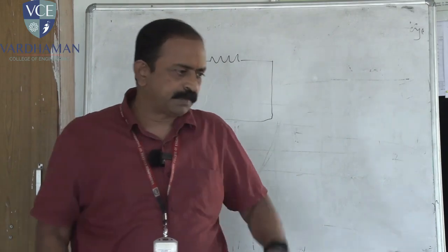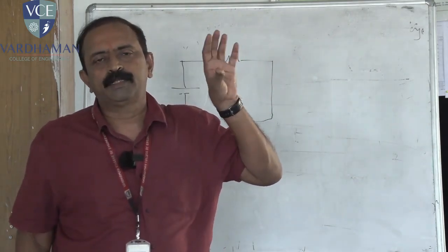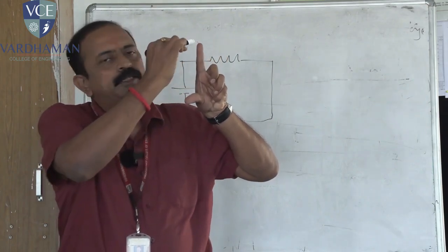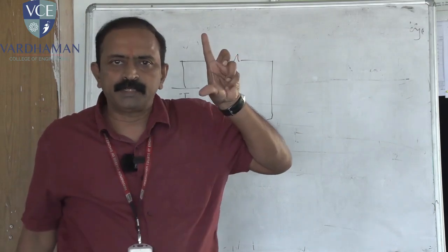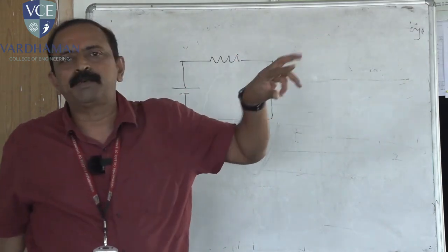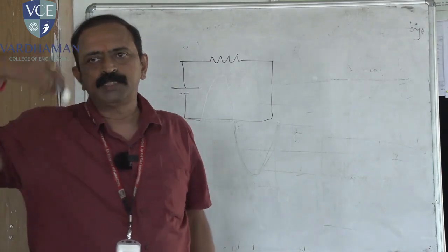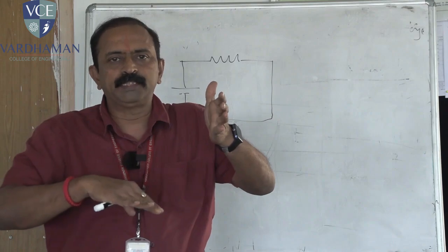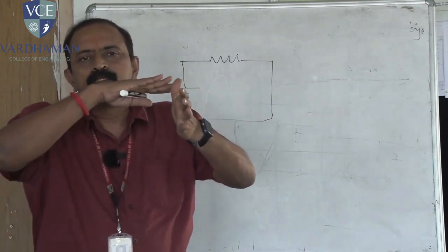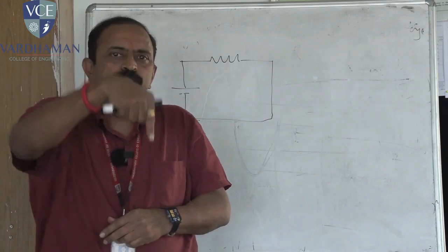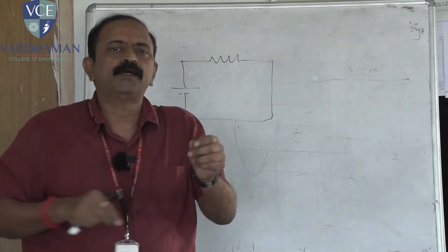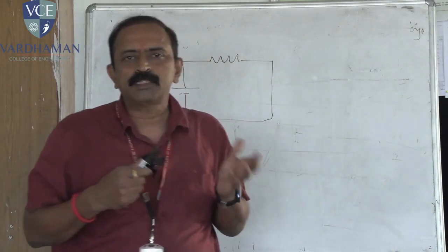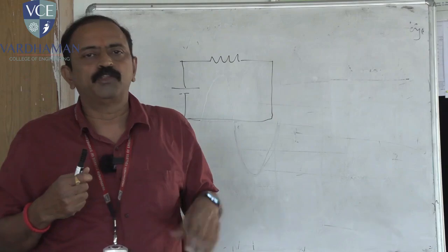Everyone should know there is an electrical socket in your home. There are 3 holes in that socket. One is phase, the other one is neutral, the third one is earthing. That earth point is taken through GI wire, galvanized iron wire, running towards all the metal parts and buried into the pit which is outside of this building. There is a big pit, and there we fill the pit with salt, sand, charcoal, and a pipe is buried into the pit and maintained in wet conditions, and whenever accidentally some short circuit occurs, there is a heavy leakage current which is dangerous for your human body.